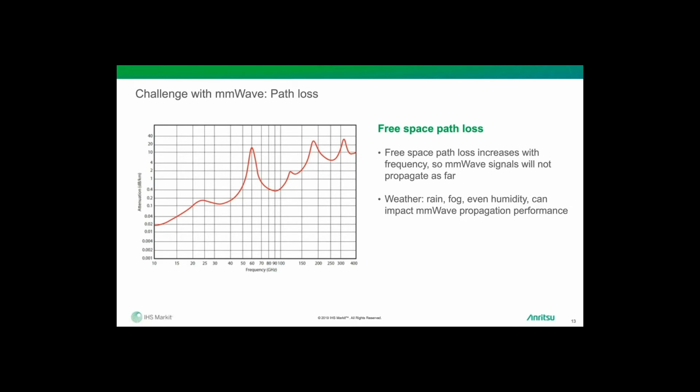As the wavelengths get shorter, the path loss through oxygen and water can get higher and higher. You have your AM radios that have been transmitting for decades, and they go for miles and miles as they transmit at kilohertz and megahertz. But as signals for mobile communications have gone higher in frequency, we've seen the densification of networks. Millimeter wave represents a new level to that same challenge and is going to require some different solutions.